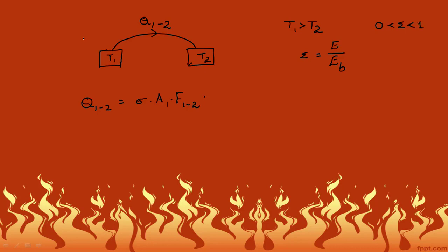If we consider white bodies, they have zero emissivity because white bodies simply reflect the energy. A black body will have an emissivity of 1. The remaining objects are colored bodies or gray bodies, whatever you call them, and those will have emissivities in the range of 0 to 1.